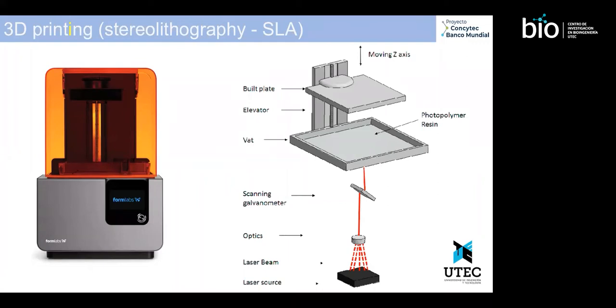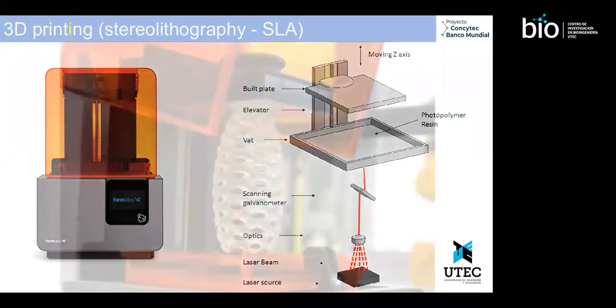So you have to go back to your drawing and change the sizes to make sure you get the sizes you really want. So it's not all straightforward at this scale. Since we're in the micrometer scales, the channel width is 200 micrometers. The channel height is also 50 to 100 micrometers. So these are the scales we're talking about.